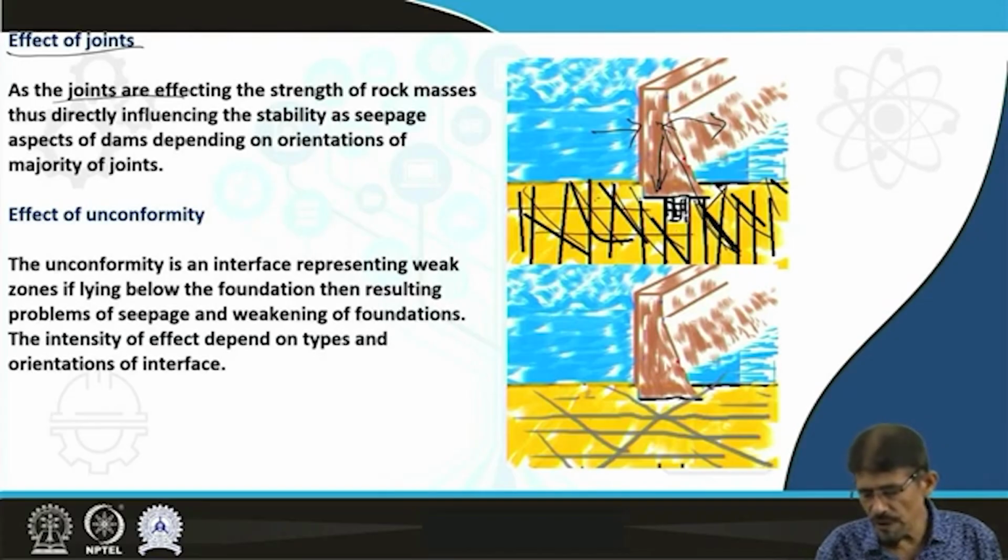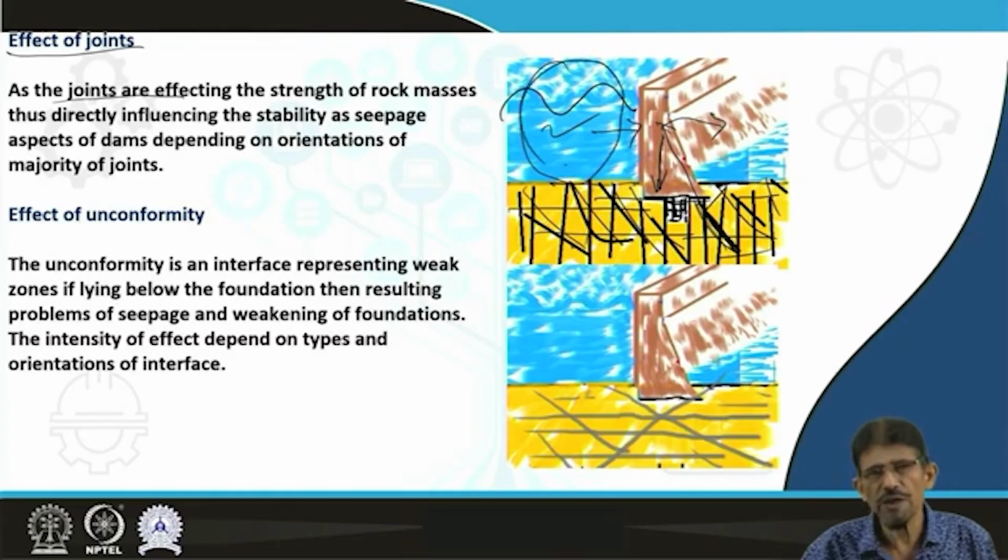But the presence of joints is going to influence the strength of rock, therefore careful treatment and preparation are required for jointed rock to ensure sufficient strength of the rock strata lying below the foundation of the dam, which can bear the resultant effect caused by the weight of the dam as well as the thrust caused by the hydrostatic effect of the water present in the reservoir, as well as, from time to time, the impact of waves due to wind in storm and normal conditions, or agitations creating hydrodynamic force during an earthquake, as well as sometimes, in cold regions, the formation of ice and others that create pressure due to expansion.